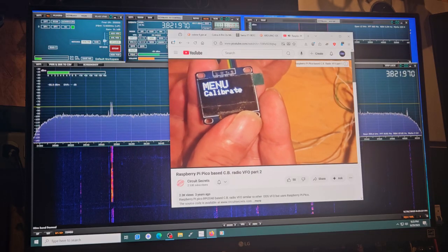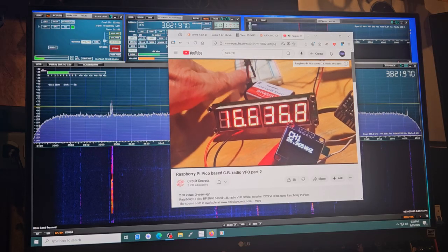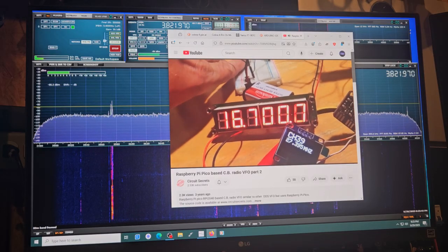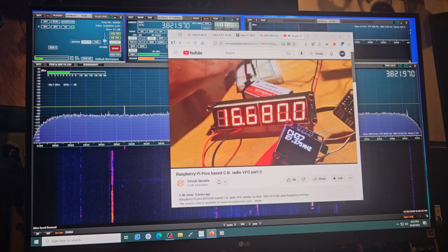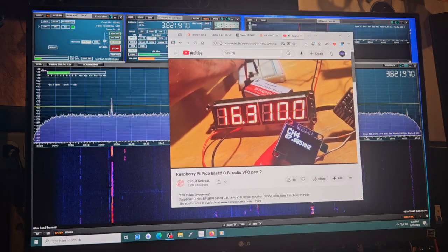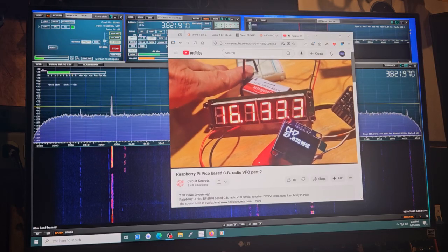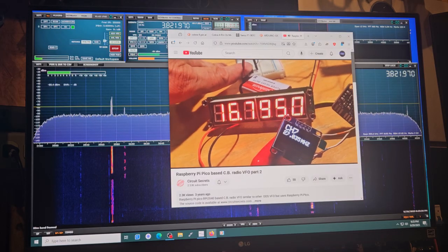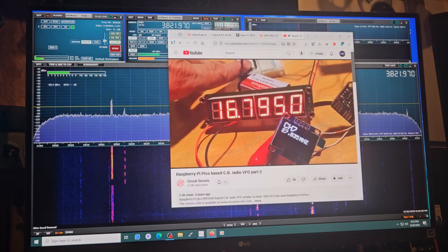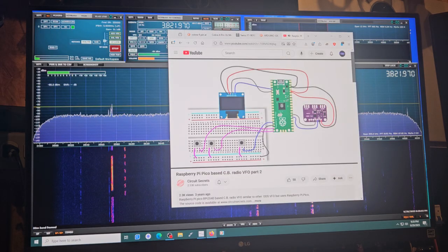In the last video, I showed you the source code and wiring diagram of the working VFO, but now it is improved with a menu that allows calibration of the SI5351 while in operation, and can save and load the calibration settings. The transmit and receive offsets are still hard-coded and must be set at compile time. This was done to avoid adding another switch to allow the large changes in frequency needed for adjusting those settings. Here's the wiring diagram. Now, into the code.